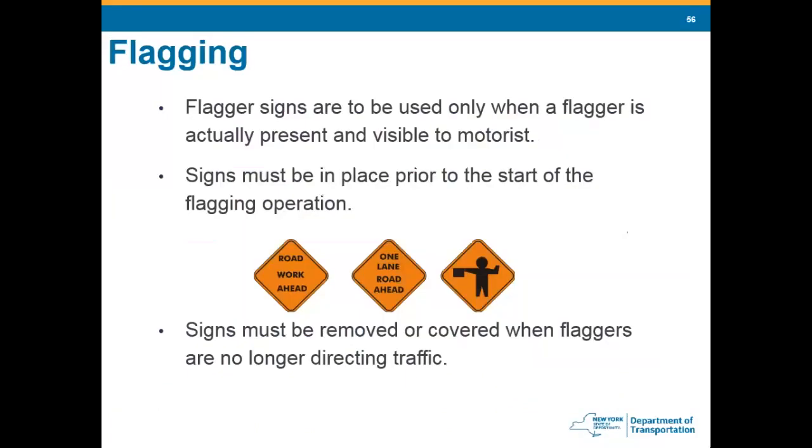Flagging. Flagging signs are only to be used when a flagger is actually present. How often have you driven down the road and seen a flagger sign set up and there's nobody standing there? You just lose credibility so fast. I mean, I drive down, I see the sign, I slow down. I don't see a flagger, I speed up, and then a half a mile ahead, there's a flagger standing in the middle of the road.